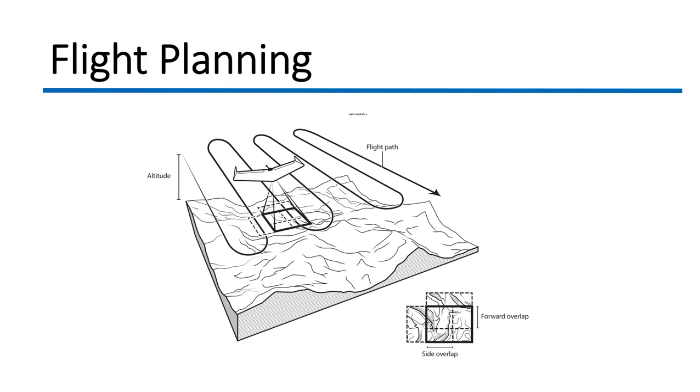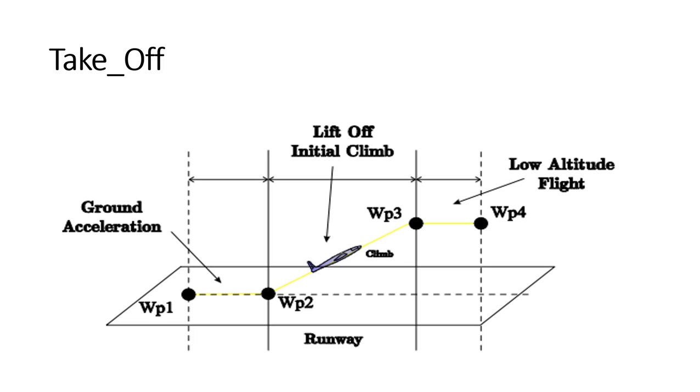In our party today, we're going to use a fixed wing to take off and fly an autonomous mission. The basic idea when it comes to using fixed wings to take off involves setting up a few parameters. As I said, every takeoff requires some bit of information. In our case, we are using a fixed wing that requires a runway, so we need to have an acceleration on the ground. And then once we take off, we navigate to the various waypoints.